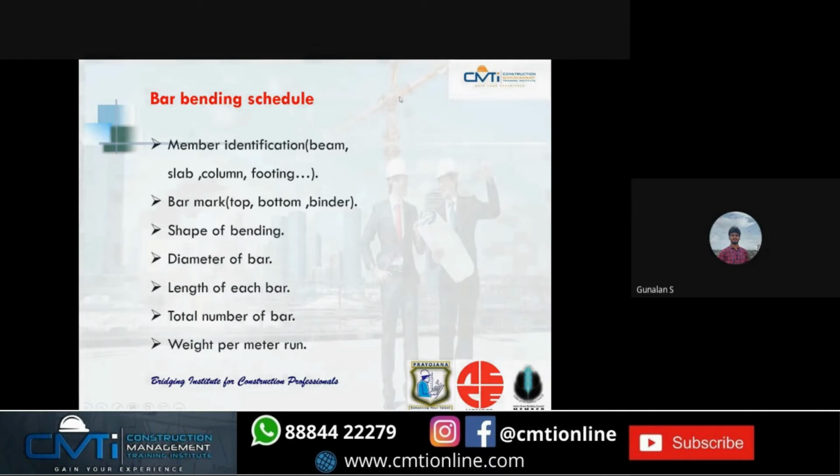Bar bending schedule was also taught by Anantanayan sir. First of all, we should determine the member for which we are going to schedule and determine the amount of bar. Next, the bar mark: top, bottom, or the binder. Next, shape of the bending, which depends on the type of the column or the footing. Next, the diameter of the bar, whether it is 8 mm, 10 mm, or 12 mm bar. Next, the length of each bar. Then the total weight per meter run is an important aspect. This can be calculated by the formula pi d square by 4 into the density of steel. Here the density of steel is around 7,850 kg per meter cube.